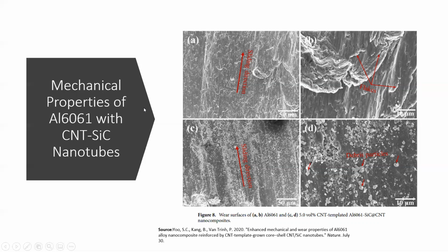For pure aluminum, large portions of material are removed by periodic delamination fractures during plastic deformation, as seen here. In silicon carbide nanocomposite, surface presents improved wear properties. Debris particles are uniformly distributed and act as hard abrasive particles with limiting material loss. Furthermore, no delamination is observed. Wear mechanism of the composite is predominantly abrasive, whereas pure aluminum alloy shows delamination and deformation.